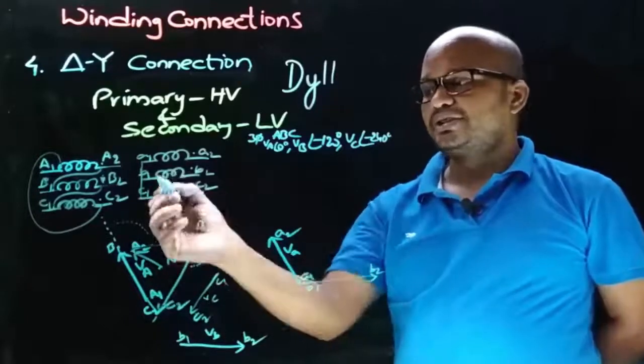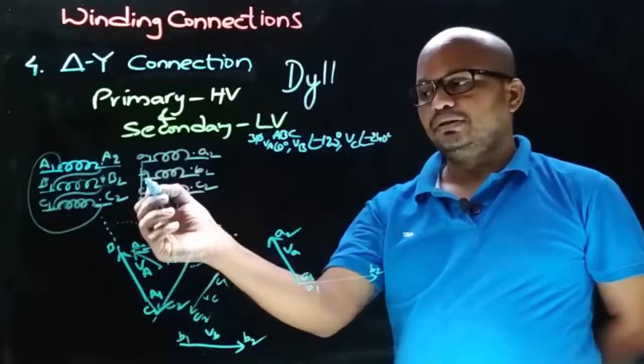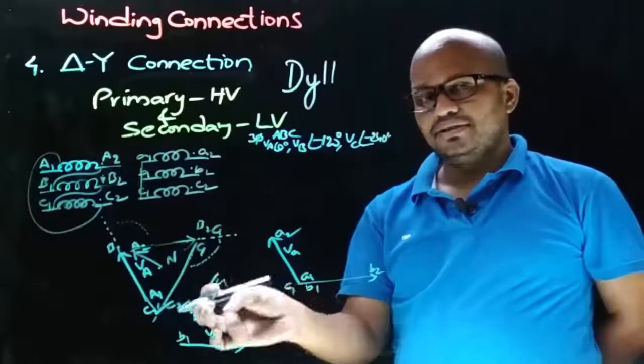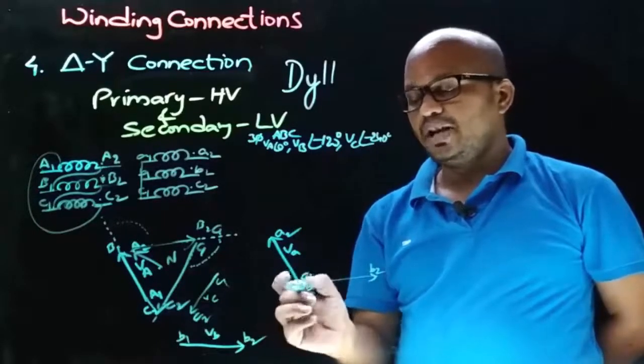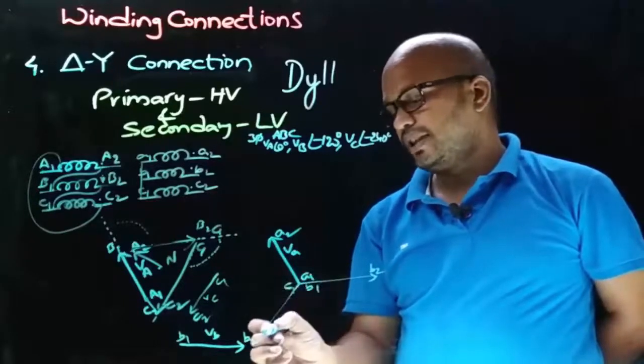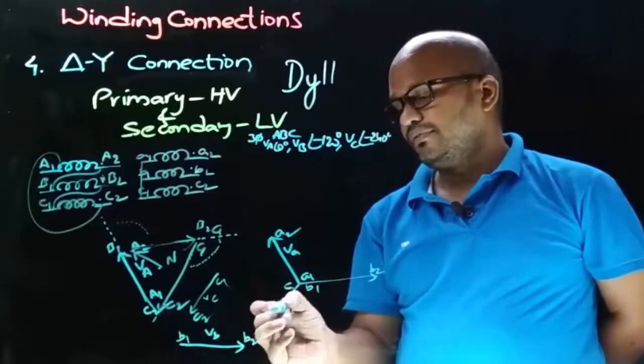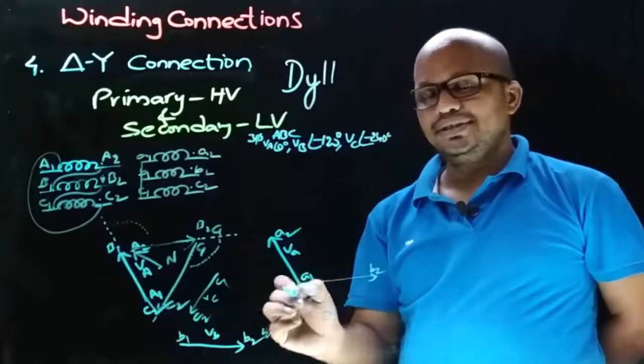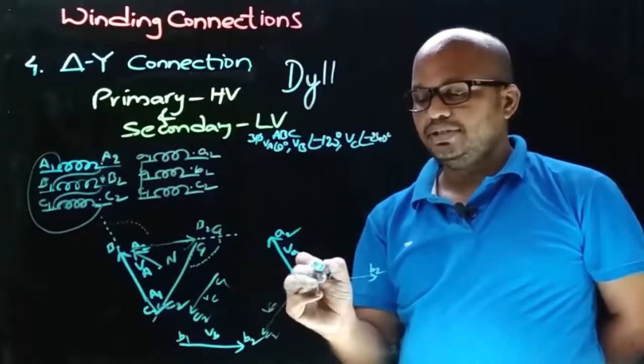And observing the winding connection, to A1 and B1 there is a C1 connection, means here we will get C1. So draw this phasor such that A1 and B1 will have C1 terminals. So like this. This is the VC phasor and the end will be C2. And now let's give the common notation for this common connection. Let that be small n.